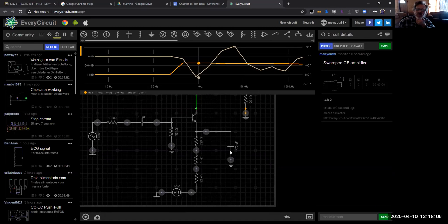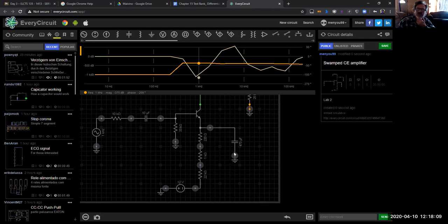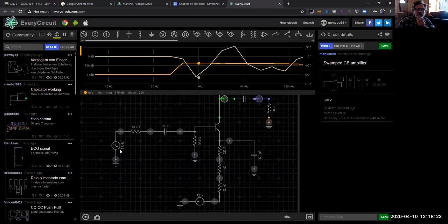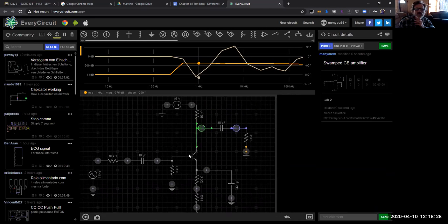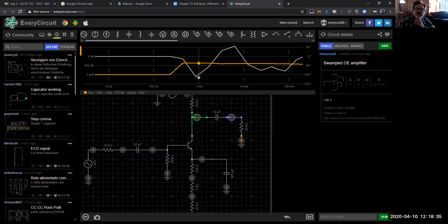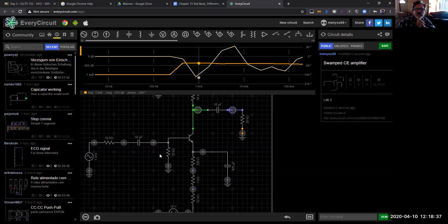We could change the values and such, and again, notice my orientation. There is my VEE, and remember, it's got to be a negative supply in, so the positive would go to ground. There's my function generator, so our AC signal coming in, and then our VCC has to be positive going in. You can even look and ask, does this thing work as intended?